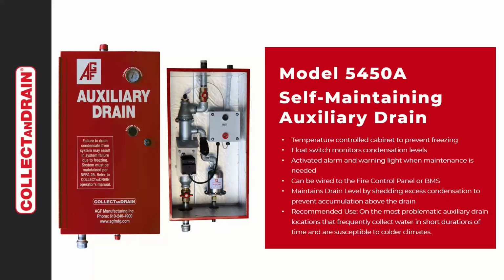So there are products available. They are called heated low point drains, and we now make a few different ones. We have a whole line, and you can go to collectanddrain.com and see some of the different styles of low point drains that we make. We have some that will literally drain themselves. We have two. This first one is a mechanical methodology called self-maintaining low point drains. Once it gets to a certain amount of collected water volume inside it, for every additional drop into it, a drop can drop out of it. So it always has some amount of water in it.